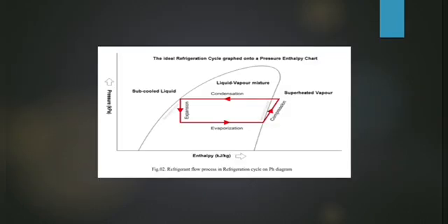The external source, the compressor, maintains two pressure zones and pushes the refrigerant to carry the heat energy due to temperature difference. During the evaporator process, the refrigerant boiling temperature is very low and the evaporator cabinet's temperature is set at a high temperature. This creates a temperature difference and heat energy flows from the evaporator cabinet to the refrigerant. Therefore, heat transfer takes place from high temperature to low temperature in both processes, in the condenser and also in the evaporator.